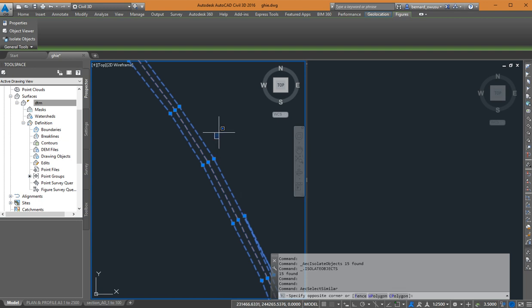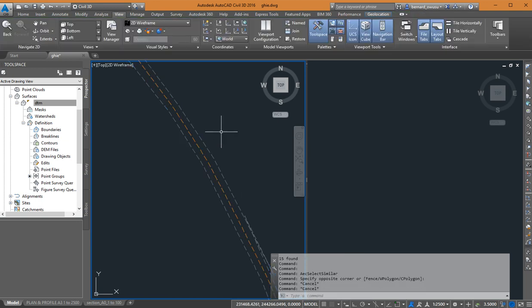Select just the line, the edges. Select the road edges and the center line. Maybe you have selected something more than that. The center line and the road edges. Then right click, select similar. Successful. Please, can we continue? Amma, successful. Okay, so you have only the edges and the center line showing. The rest are all hidden. So, can we continue?